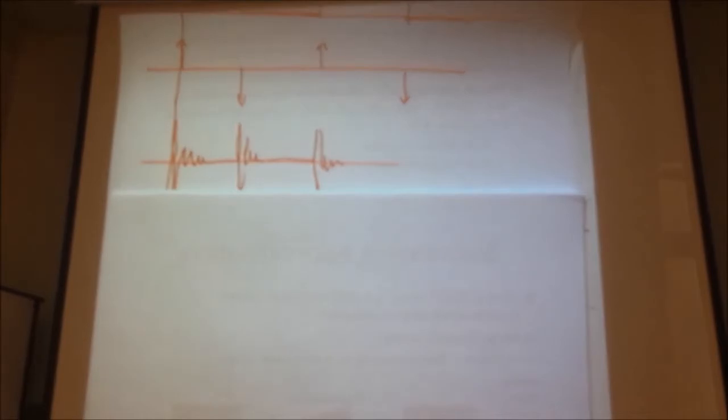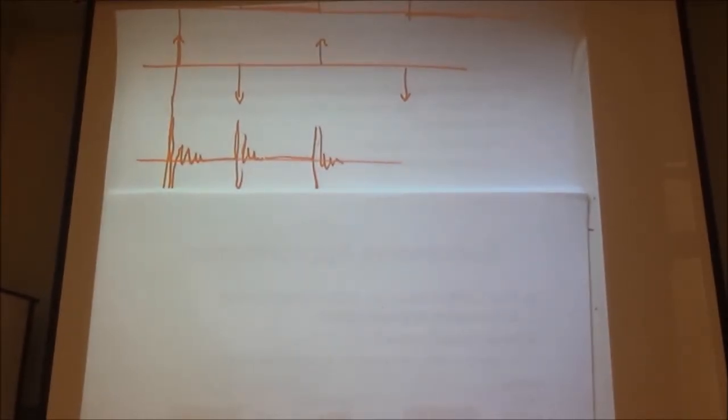But really, when you apply a voltage input to an op-amp, for example, it takes some finite amount of time for the op-amp input to reach that applied voltage, because there's internal capacitance. That finite time slows the switching speed. It gives you an upper limit of how fast that op-amp can behave. And when you get down to transistor level, that's a big factor as well.